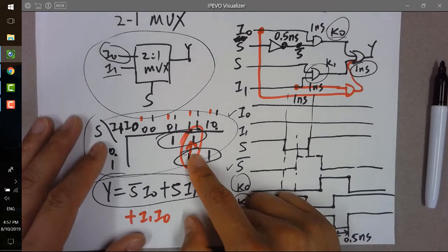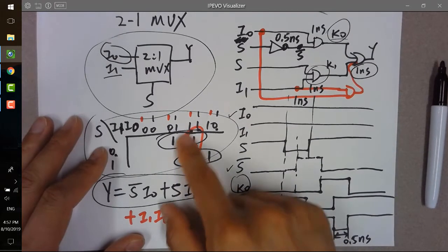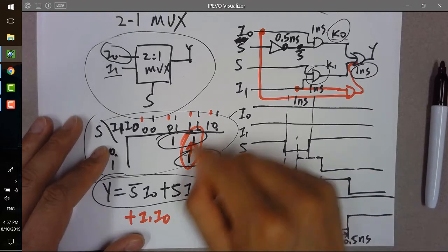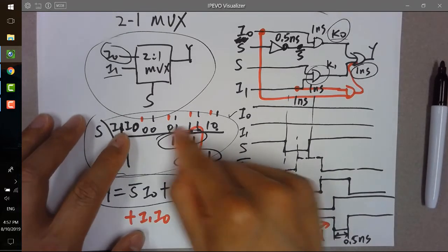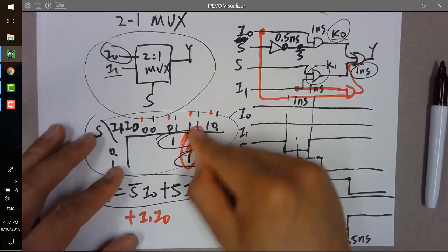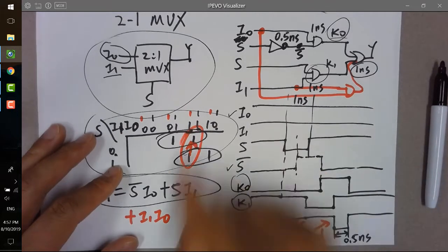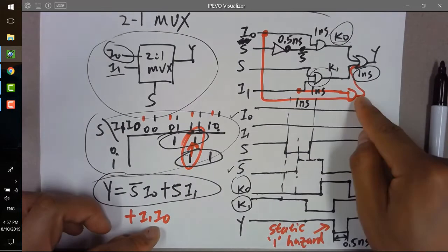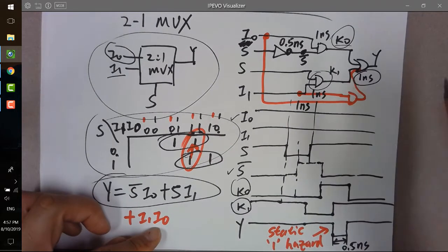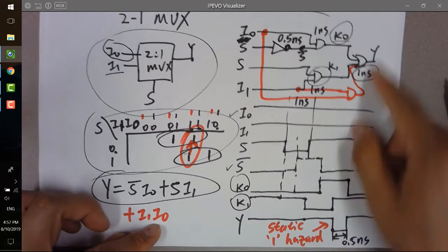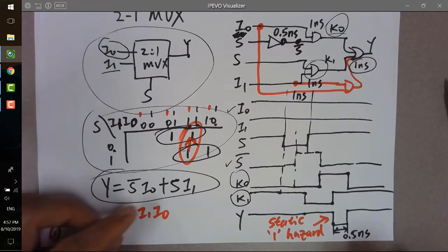The reason you can get rid of it by grouping these two is when this state jumps to this state, you have your I1, I0 always be 1, right? So you just add it to there, so you can add a very strong logic 1 to the OR gate, which will hold it to be 1 all the time and won't let this dip happen, okay?